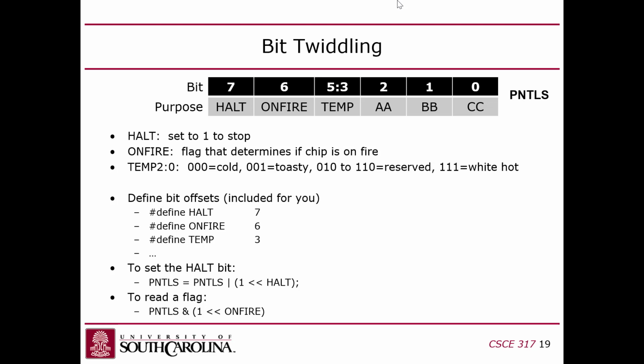So for example, I made up an I/O register, which is 8 bits, bit 7 down to 0. Now, the most significant bit 7 is on the left, the least significant bit 0 is on the right. So the bits are labeled up here, and then below each bit is a symbolic name for that bit or that bit range. And this is how, when you look at the user guide, the data sheet for the processor, it represents all of the I/O registers this way, right?